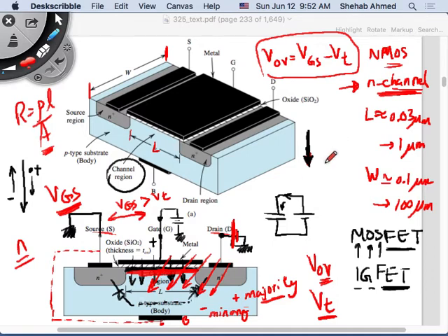You have another one due to the voltage I'm creating with respect to ground, but also the source is at ground potential as well, right? So I have an electric field that can be emanating this way or this way, right? So I have an electric field out of this drain. Assume now that the vertical component here is neglected because I don't really care. This is a reverse bias diode, right? So current will not flow out of here into the P region.